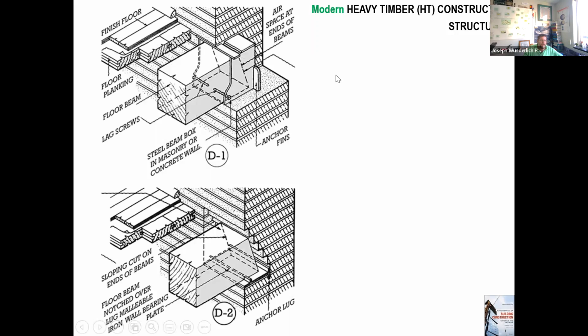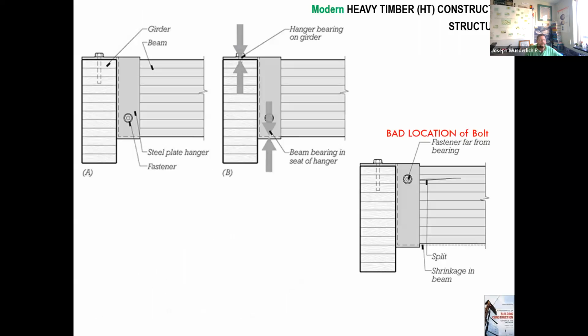And this is something that can be even more serious in masonry buildings, especially unreinforced masonry, but assuming this is reinforced masonry, these kinds of connections can become critical because masonry can crack and chip, and this heavy load of a girder is sitting here, even though you're spacing it back. If you don't do this kind of thing right, this could fail very easily.